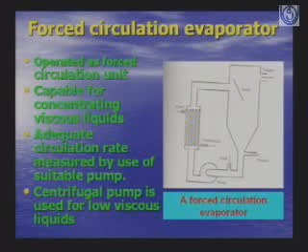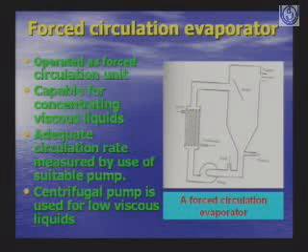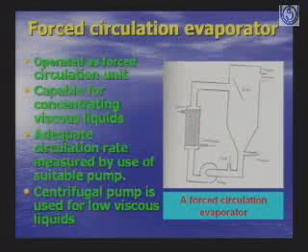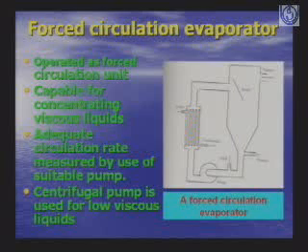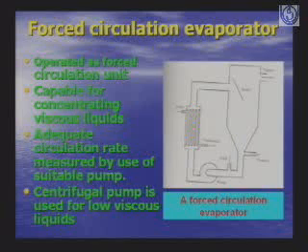These operators are capable of concentrating viscous liquid materials. Here, adequate circulation is maintained, and the circulation rate is measured using a suitable pump. Here the centrifugal pump is used for low viscosity liquids. In the figure you can see the forced circulation evaporator.